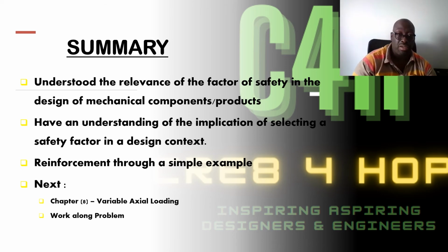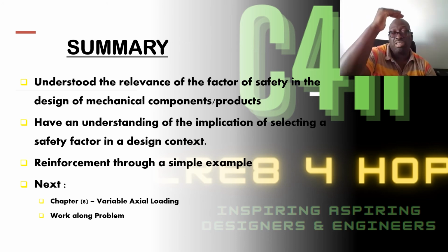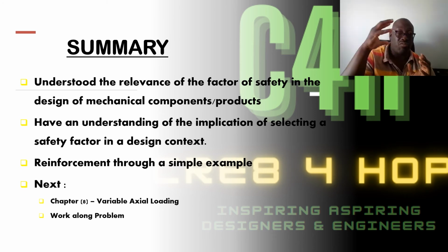So as I pointed out, it's very important that we somehow find a way of quantifying these measures of uncertainty that are very difficult to capture when it comes to mechanical design analysis. And this is where the safety factor gives us some measure of guarantee of the operability of the material, in terms of how the material is deforming well below the yield limit of the material. Thus, it's operating adequately within the elastic region of the selected material. Thus, when all loads are taken off, the material has time to ideally recover back to its original state.